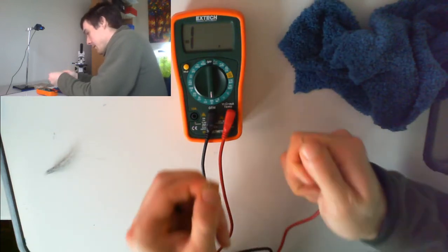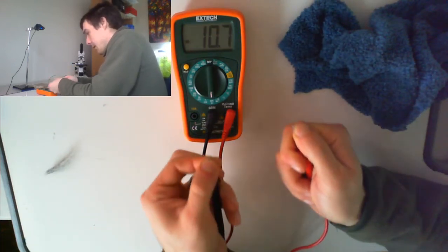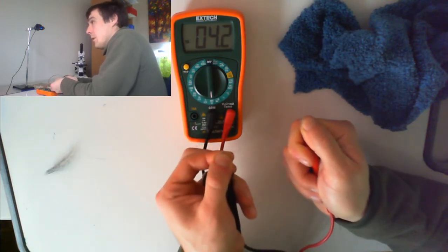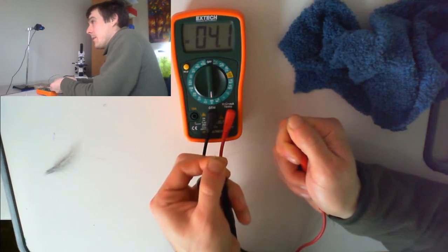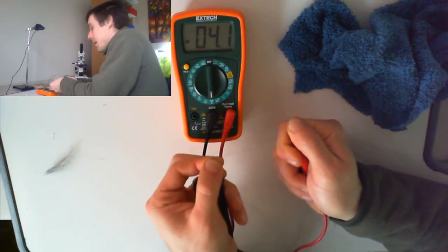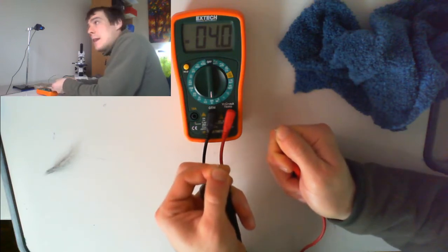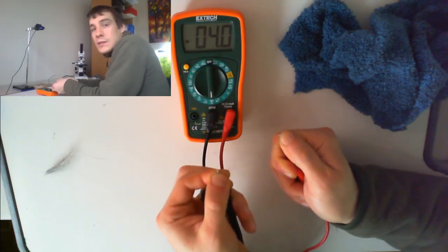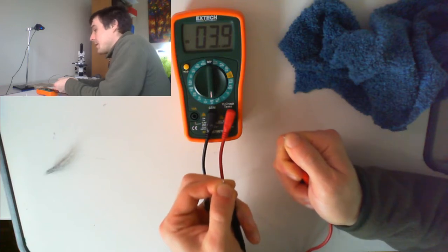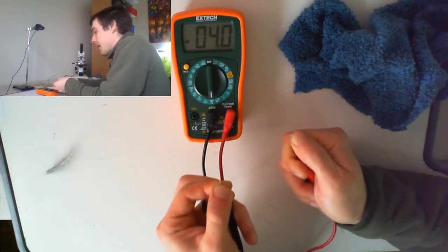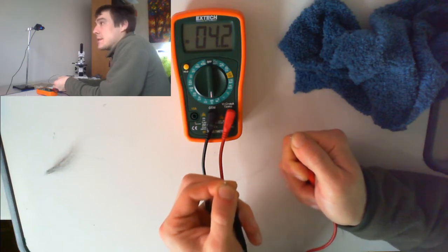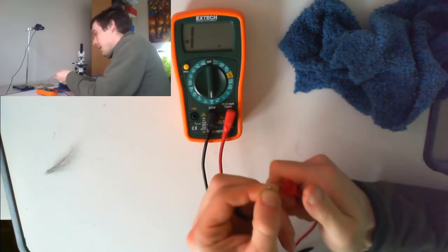If I measure the resistance, we've got about 4 ohms of resistance across that wire. Now a question for you guys. What happens if I bring these probes closer together on the wire? Do you think it'll have more resistance or less resistance? The electricity is going to be flowing a shorter path through that wire. More resistance or less resistance? Let's try it. I'm going to bring it down to about here.